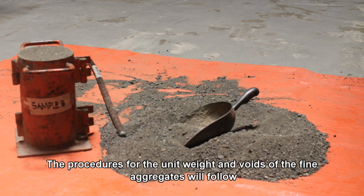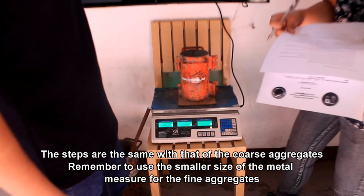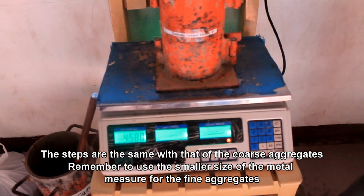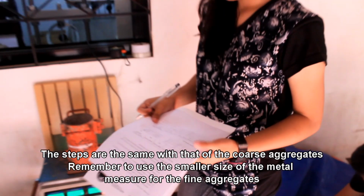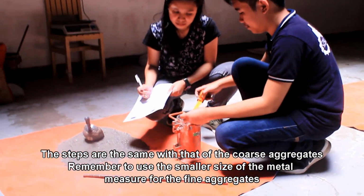The procedures for the unit weight and voids of the fine aggregates will follow. The steps are the same as those for the coarse aggregates. Remember to use the smaller size of the metal measure for the fine aggregates.